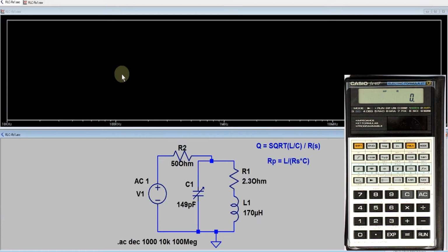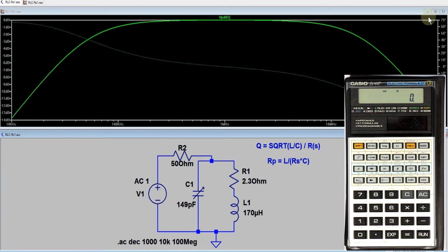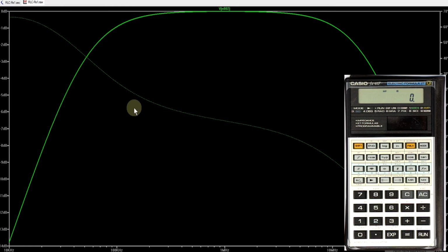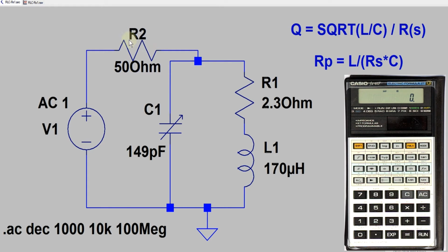Now let's do the simulation. We take the voltage here at the upper point of the tank circuit, and oops, what is that? This is a bell shape, okay, as we expect. It's also centered at 1 megahertz, but there is no sharp resonant point, so we must have done something wrong with our test circuit. And I've just put this in as a trap for young players, so just take a thought where the error is lying.